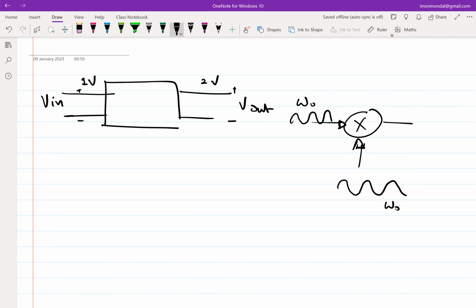If you break sine squared, what do you get? You get 2 terms. You can get a DC also, right? So in the input, you didn't have any DC. Inputs are pure sine. The output, you can get a DC, right? So now let's say for all practical purposes, I put a band pass filter or a low pass filter at the output, and I am only observing DC.